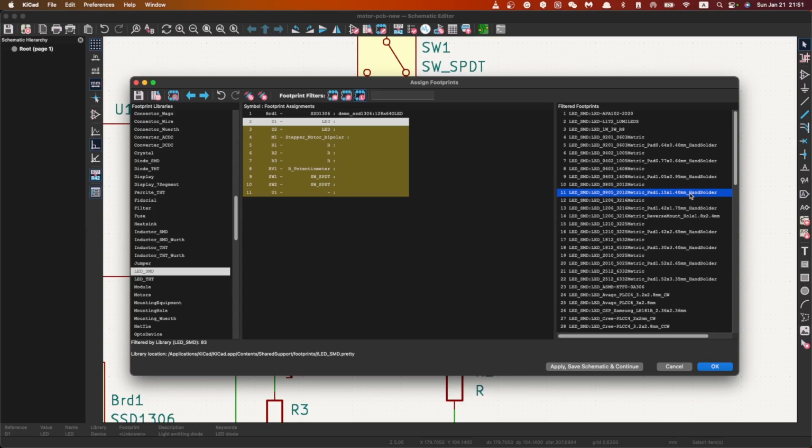0805 is the largest one on that board. The smaller one in the middle is 0603, and the smallest one there on the right part of it is 0402. And I bet no one can solder that 0402 by hand without using any soldering masks or heat guns, something like that, because it's not meant for hand soldering at all.